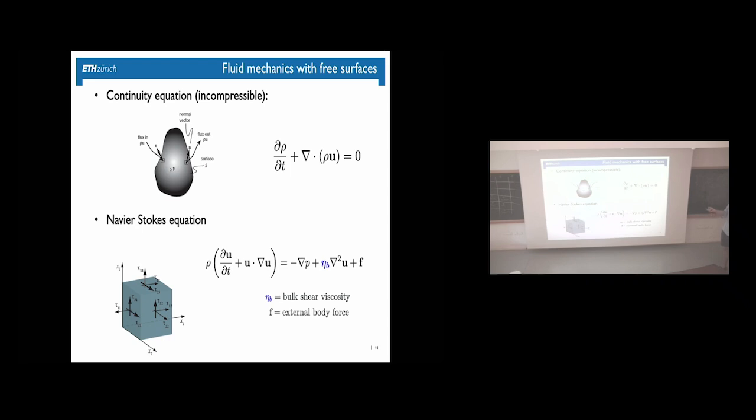I have the continuity equation, the change of density in time, and then the nabla, and then rho times u, the velocity. Most of the time we happily ignore this. We can use the Stokes equations because the density is constant. Density is constant means things are incompressible. We can throw out thermodynamics. Pressure is ill-defined. That's what we do when we solve the Stokes equation. We only care about extra pressure differences, normal stress differences, shear stresses. We don't care about the pressure in the equation of state.